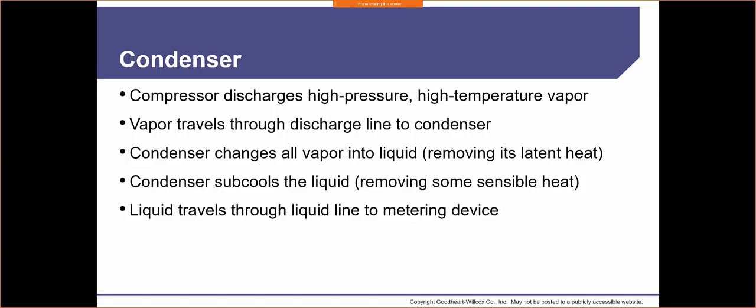All right. How do we know that we're removing this latent heat? Easy. We're going to go to our air conditioning system, our evaporator that sits above or below the furnace, and we're going to listen for water. If water is dripping out of our air conditioning system, we know it's operating.